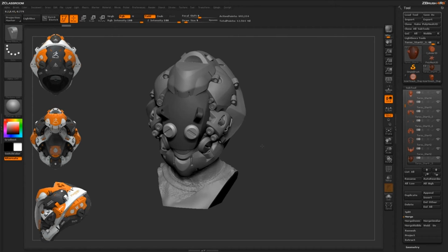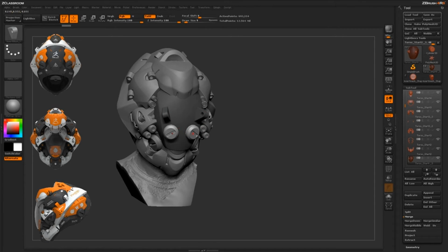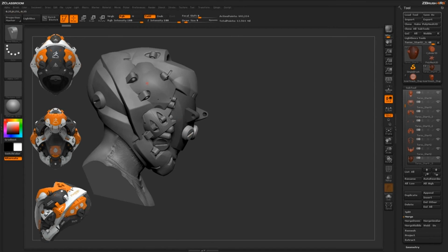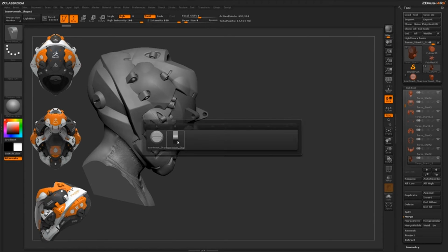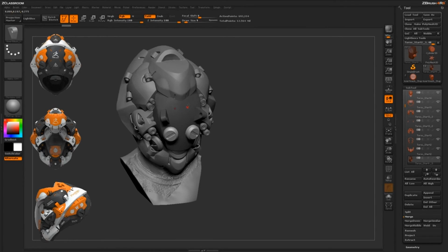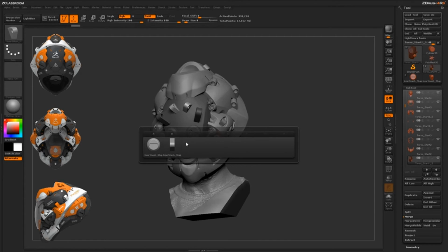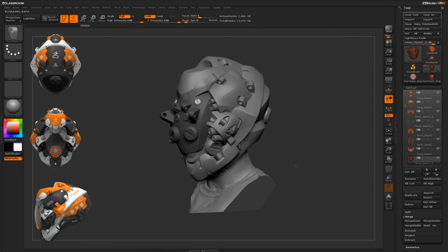Now if you want to set the depths for these, you actually have to go through and set them individually for each shape. So for this shape here, I could come up and give it a depth of 0, and then if I hit M and select the other shape here, I can give that, say, a depth of 30. And so now each of those has their own kind of depth values associated with them, so you can come through and start populating your model with those shapes.